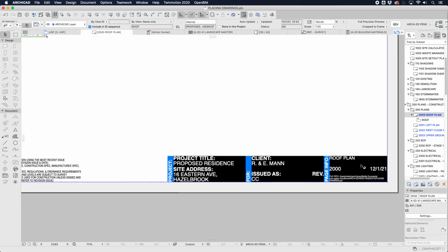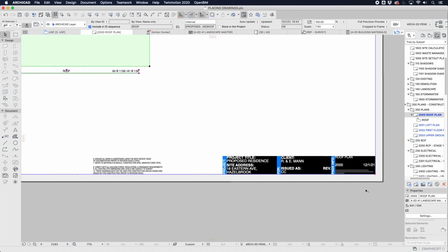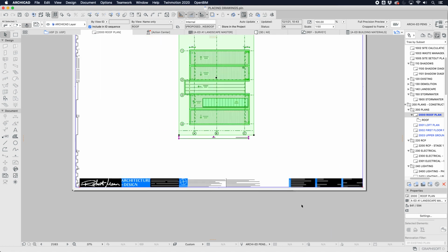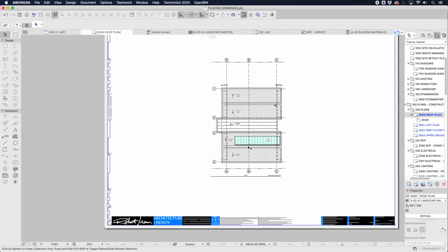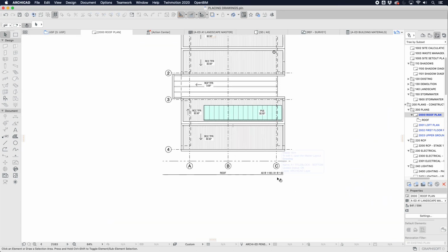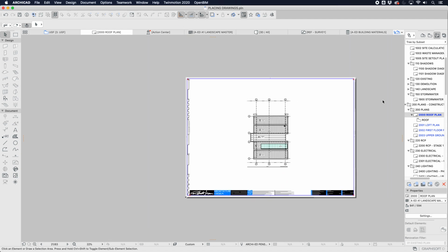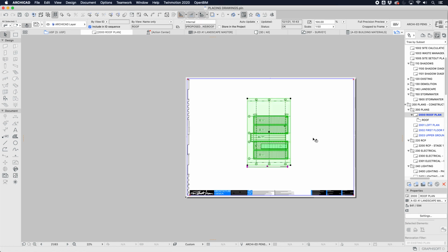If you leave this in the title block, you can of course do the name, which in this case is just based on the layout name, which I've described here. But you can't do scale really well. You'd have to do it manually. You can't do it automatically, because if I have different drawings with different scales, it's going to screw it up. It's not going to represent it properly. So next question, how do we make sure that they are all aligned?